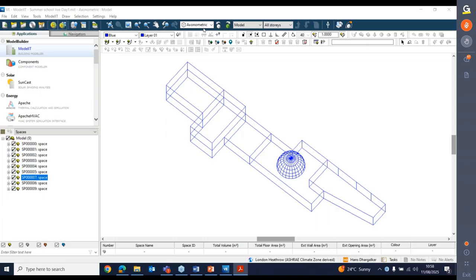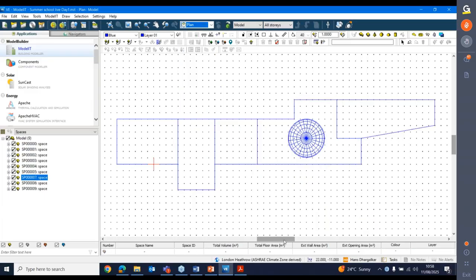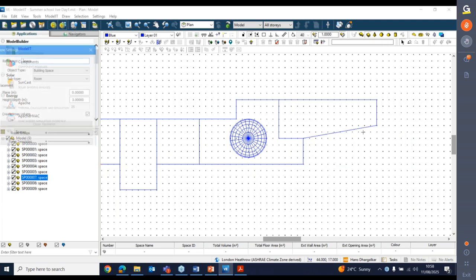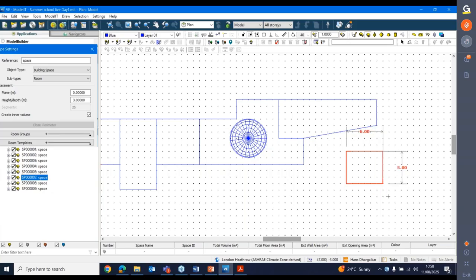There's quite a useful command you can type in. So when you draw a room and you click on the first point, you have your first point, and you can then use your mouse to define the opposite corner. Instead of using your mouse, you can type in a key-in command, which is in the format dx equals a comma b, where a and b are two numbers. And then you type the command in this box up here. Okay, you don't have to click in a box, you just start typing.